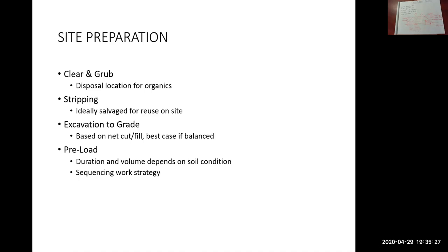So that material stays there. Of course, it's heavy. It squeezes the moisture or the water out from down below, and it will also settle. As the water is squeezed out, the road will settle. So the preload is allowed to stay there for a number of months. Usually it's 6 months or a year.